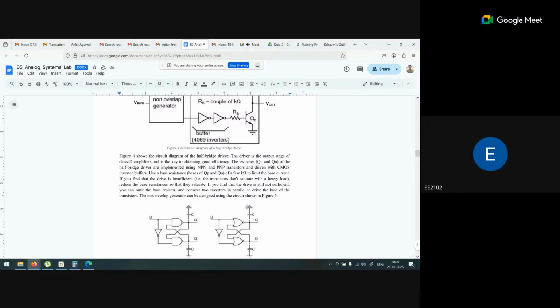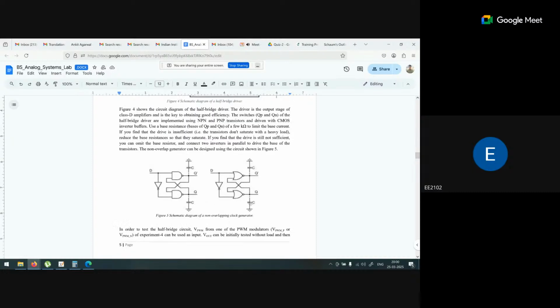So basically the circuit, if you see here, will be providing me two outputs, one is the Q and second is the Q bar. Two situations will appear: if any one transistor, basically one gate, has a high voltage, the second gate will be providing the low voltage. So it is providing two coupled outputs similar to a flip flop, two different outputs.